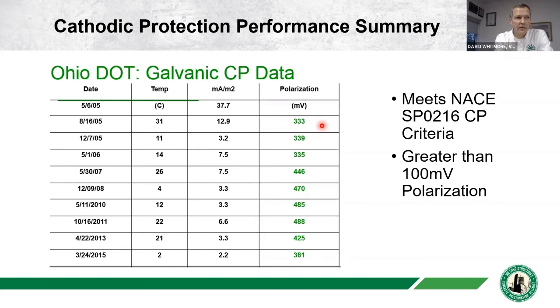You should not see that with anything galvanic. Generally, you don't have enough voltage to do that. You're going to need proper surface preparation so you don't have delamination or bubbling. But I don't think that should be an issue that would be unique to using or not using the anodes inside.